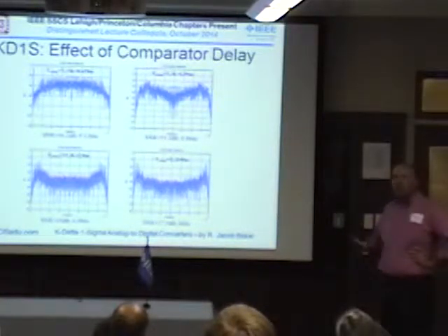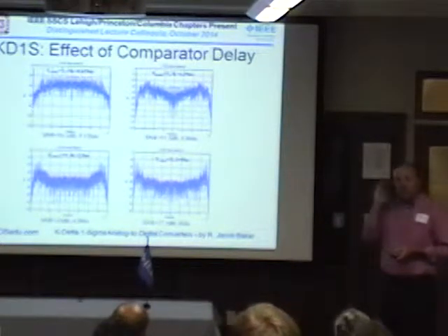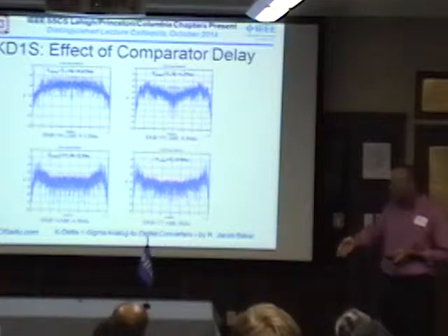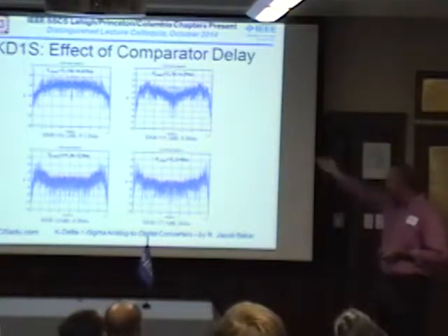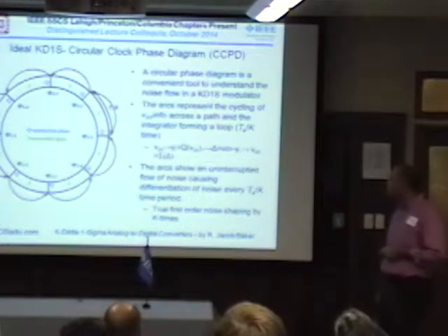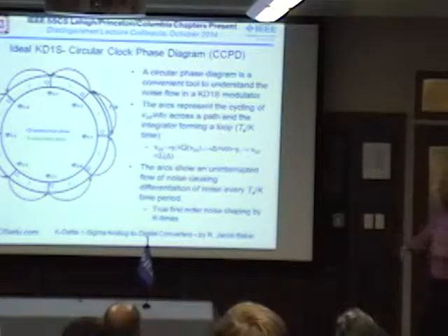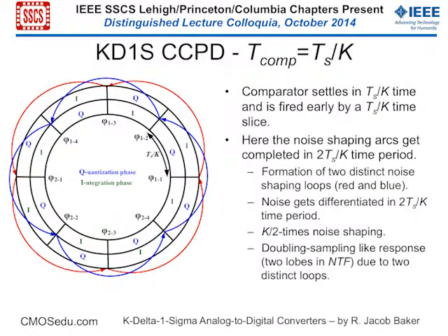In reality, you can't ever use these because you have to put some circuit on the output which gets rid of metastability, that says, hey, make a decision now, and then feed that back around so that you don't have these problems. So that's not going to happen. And then, of course, if it adds instead of removes, you get the benefit of the topology averaging things out. Okay, and so here's some more talking about the delays, quantization delays, and all that. All right, so the test results.